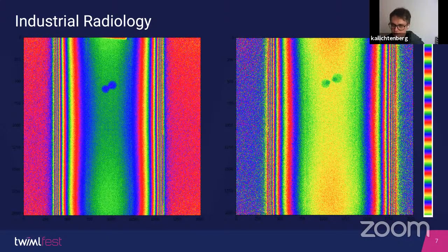Oh, there is a lot of industrial radiology everywhere. There are two different ways to do it. You can do it on site. For example, when you build a pipeline, you have people out there with mobile X-ray machines, and they take pictures of the weld seams of a pipeline. Each and every weld seam has to be X-rayed or maybe ultrasonically evaluated, but X-rays are very common here. Think about those segments being 15 to 20 meters long, and how many weld seams you have on a 2,000 kilometer pipeline. So a lot of pictures are made.